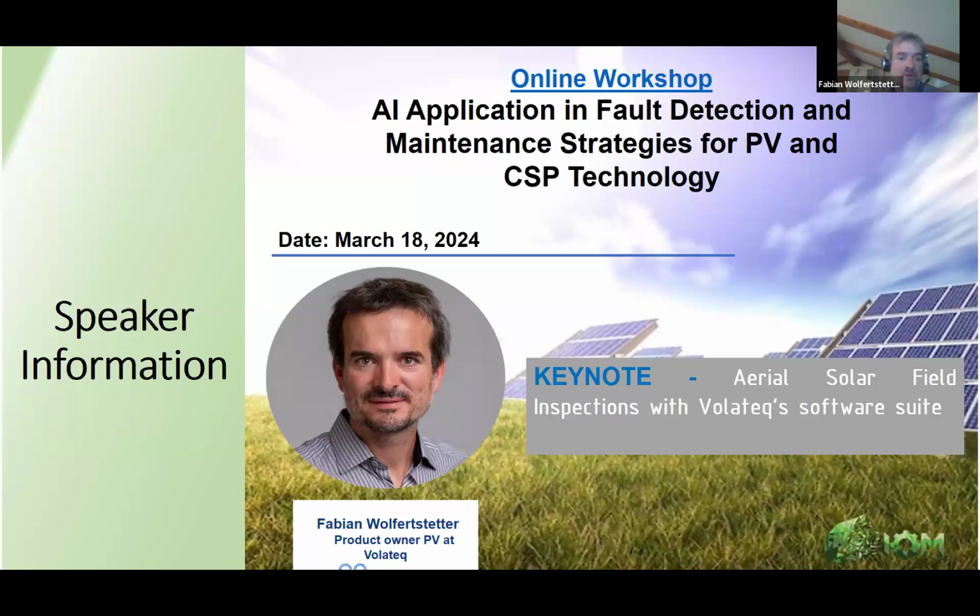Well, you always need both. You also need the monitoring because you cannot fly every day with thermography. The monitoring covers that part. So with the monitoring software, where you get all the data from how much output do you have from your solar plant, you get usually alarms if something's running wrong instantly. And with drone software, you just get it once you fly. So that's usually once a year or something.